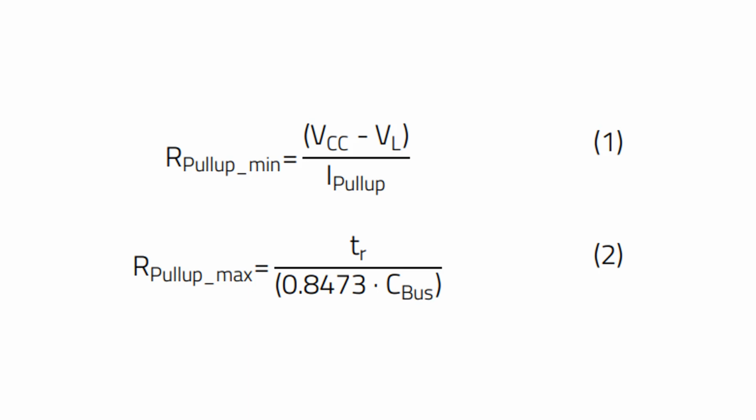The pull-up resistors, in combination with the parasitic bus capacitance, form an RC element. This leads to a delay of the edge rise time of the square signal. In many applications, this RC element is often the limiting factor regarding the maximum possible data rate and the cable length. Now, as shown in our original table, the I²C specification therefore results in a maximum bus capacitance of 400 picofarad at 3 milliamp current for the most commonly used data rates.